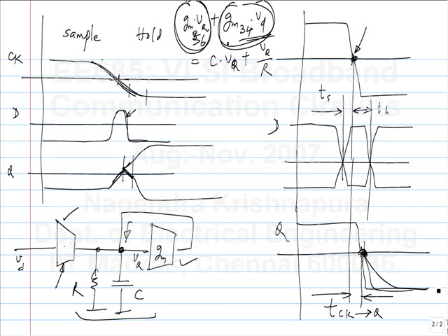So you have to make M1 and M2 faster for it to switch from one phase to another, and M3, M4, M5 and M6 affect them in individual phases. But again, if you make M1 and M2 larger and larger, they will switch faster. That is, they will switch with a small threshold voltage. But the problem is that it will increase the loading on the previous stage.